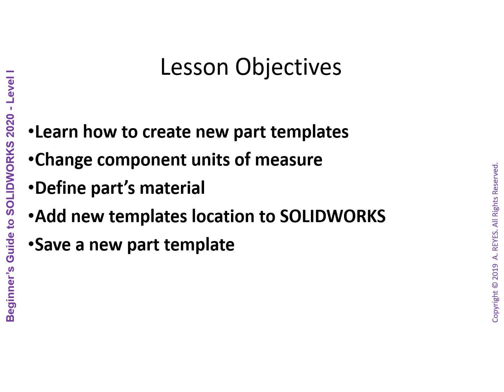Right, now we'll look at the video on how to create new part templates, change the components used as a measure, define the parts and materials so you can change it to things like wood or metal, add new templates location to SolidWorks, and save a new part template.